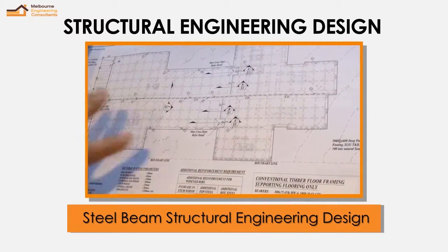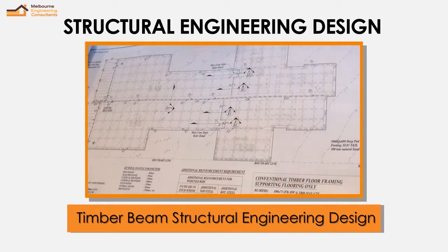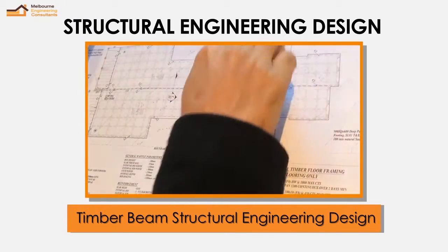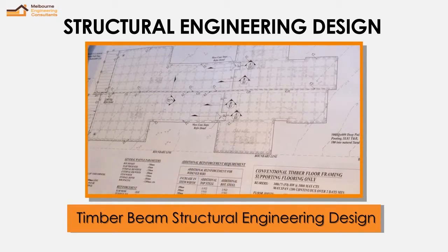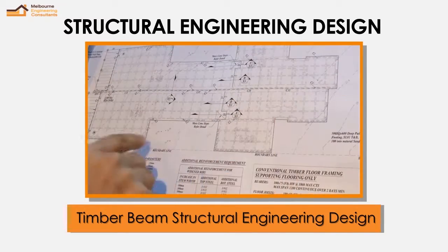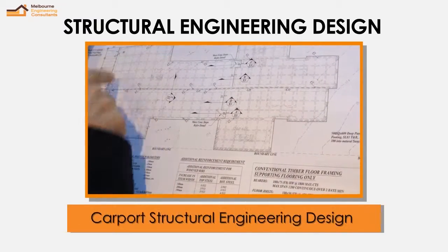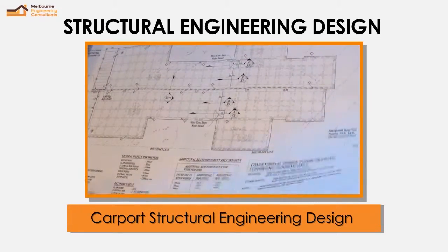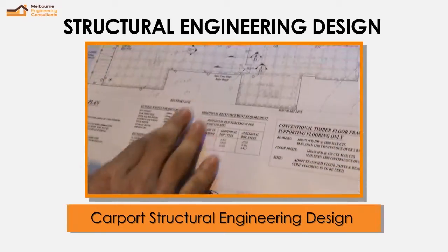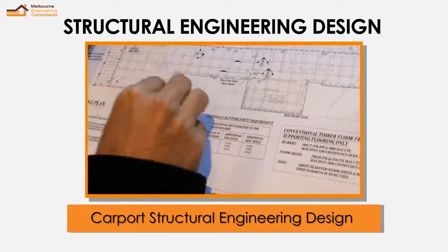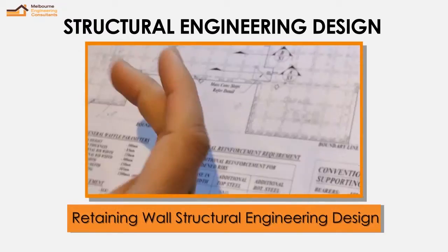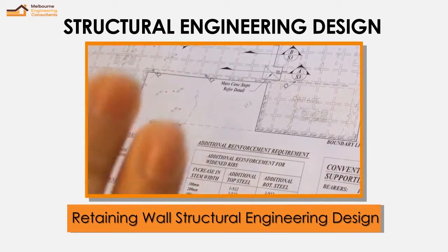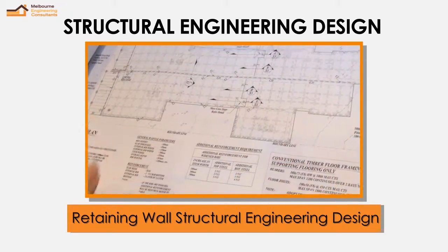This is the typical set of the structural drawing showing the footing, where we have this garage slab here, typical step down details. We have 2 units side by side, and at the back we have the timber decking. And here we have typical details for the same footing, what kind of requirement is needed, like how deep the waffle pods will be, reinforcement, and the conventional decking slab required.